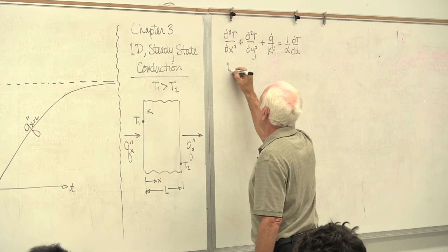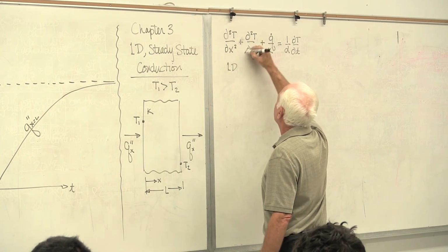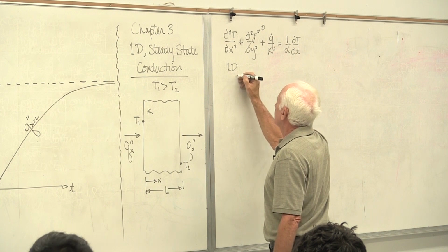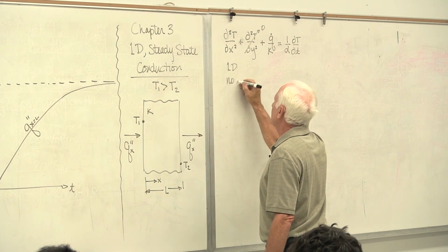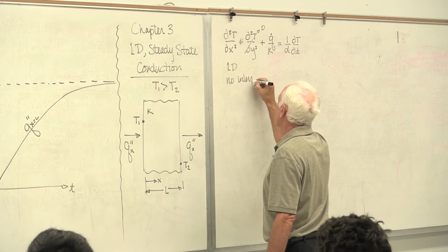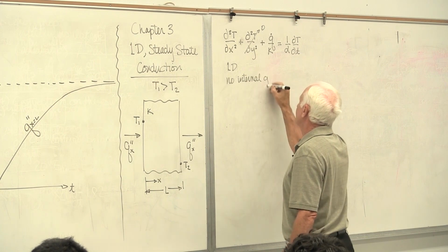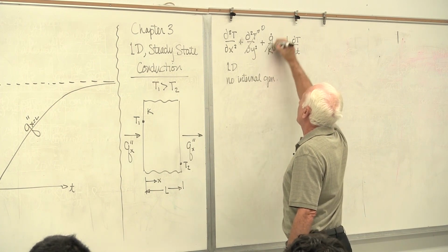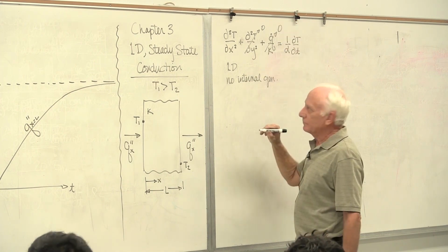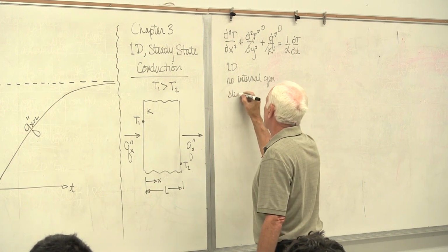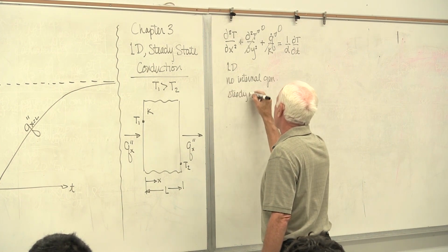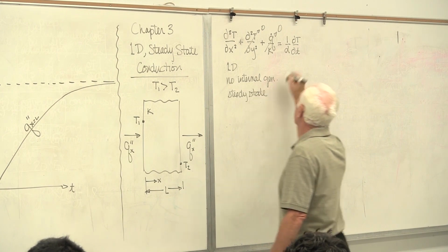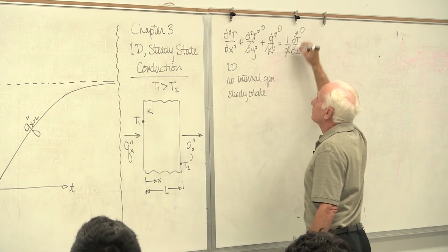Okay, 1D. That term goes to 0. No internal generation, no q dot. That term goes to 0. Steady state. That term goes to 0.